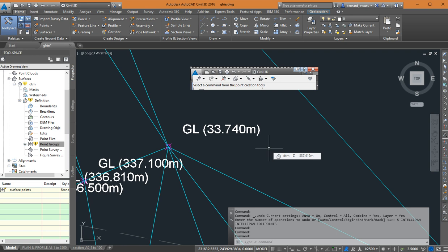When you do it, you realize that there is an out of date symbol before the surface that you created. It's yellow. Can you see it? This yellow with caution means out of date. You will not only see it here. Wherever there's an opportunity for regeneration, if it is out of date, you see the symbol. It's telling you that you have to update it. Please, can we continue? Good.